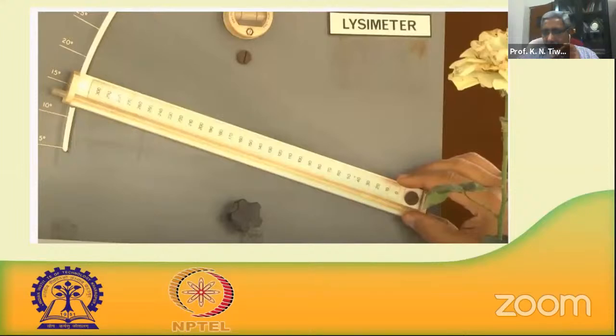This is not 1200 millimeter amount of water needed by the crop. It is not a standard value, I should say. It will change as per the agroclimatic region, as per the soil, as per the specific variety, and in which season the crop is being grown. That is one thing. Now, part of the rainfall which occurs in a year will be a contribution if the crop is grown in that particular season. That will contribute, but one has to add additional water to meet the evapotranspiration or water requirement of the crop.